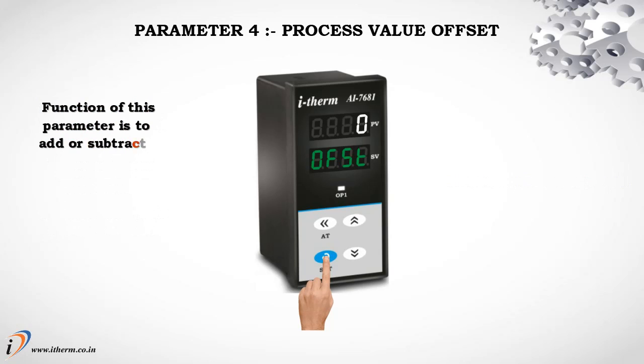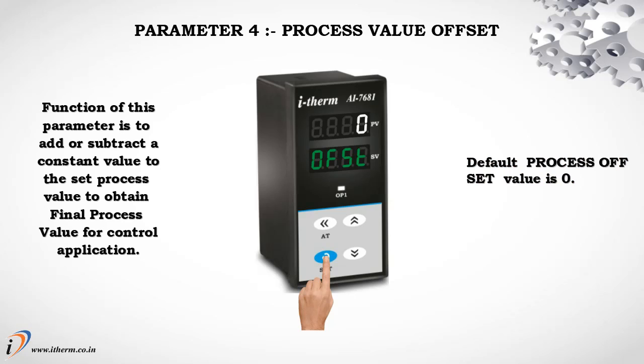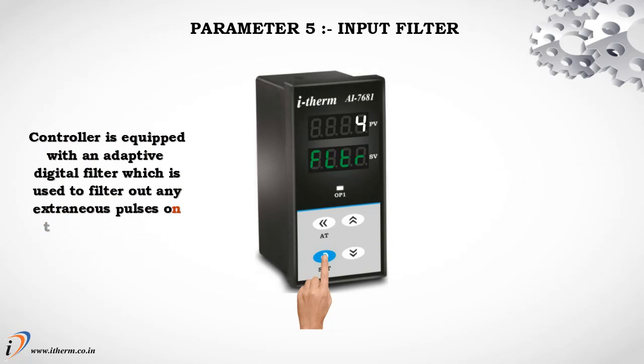Parameter 4, process value offset. Function of this parameter is to add or subtract a constant value to the set process value to obtain final process value for control application. Default process offset value is 0. Parameter 5, input filter. Controller is equipped with an adaptive digital filter which is used to filter out any extraneous pulses on the process value. Default input filter value is 4.